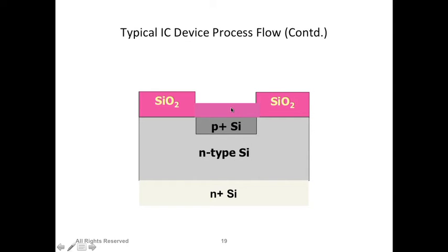How can we deposit silicon dioxide? You will tell me. Oxidation or PECVD, for example. Two choices. If I want to deposit silicon dioxide here, can I use oxidation or do I need to use PECVD? We can still use oxidation in this process, right? Because you have a silicon source at the bottom. And we can also use PECVD. With PECVD, we don't really need silicon, but you can still deposit silicon dioxide on top of silicon with PECVD.